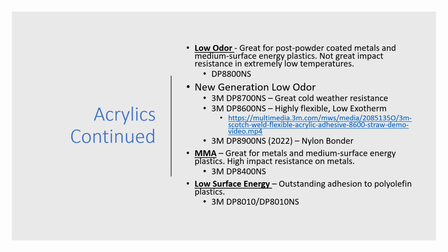When you're bonding thin gauge metals or thin gauge materials, and there's heat released, it will expand and then contract back to its original shape. It can leave ripples or a dimpling effect on the surface. This is called read-through. So if aesthetics are important, you definitely do not want to spec in an adhesive that has high exotherm if it's a very thin gauge material.